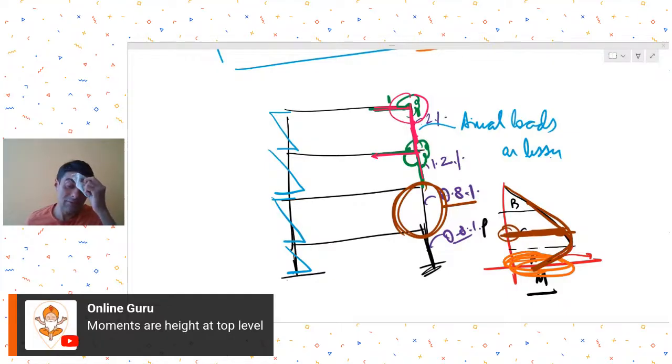So this is the reason why you may see this in mid to low rise buildings. Now in high rise buildings, when you go to the lower floors, because of the very high axial loads, you are again in this region. So again the moment capacity is lesser because of very high axial loads. Because the moment capacity is lesser, again you will see more reinforcement percentages.